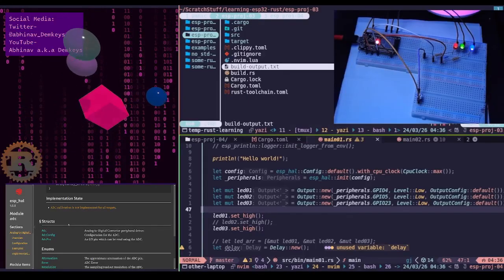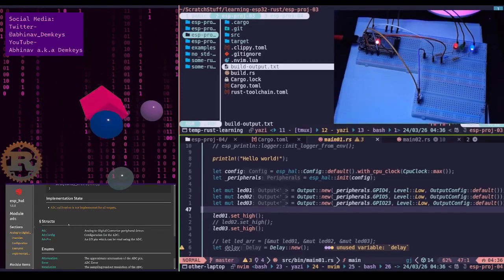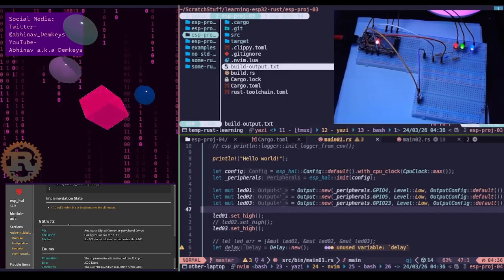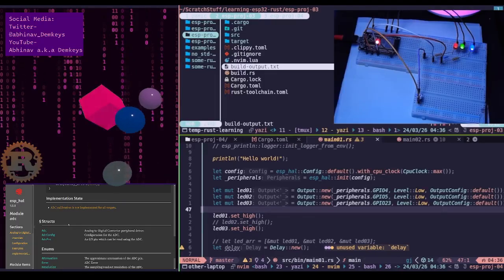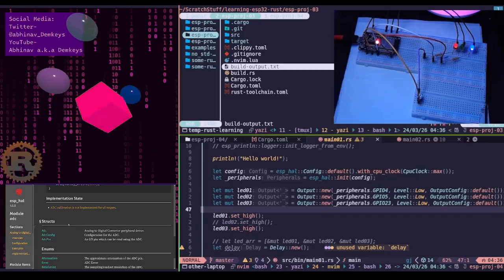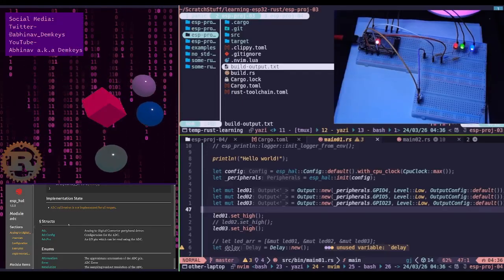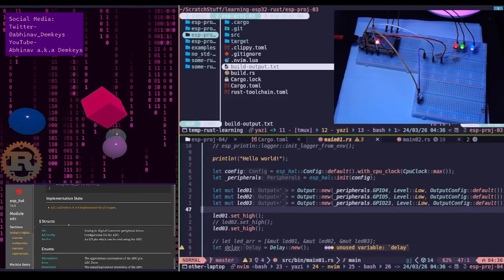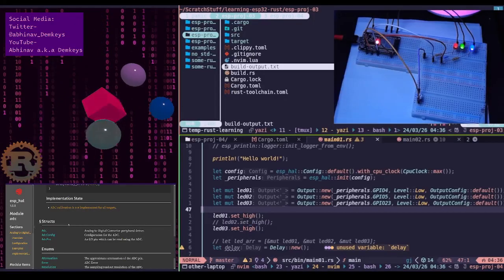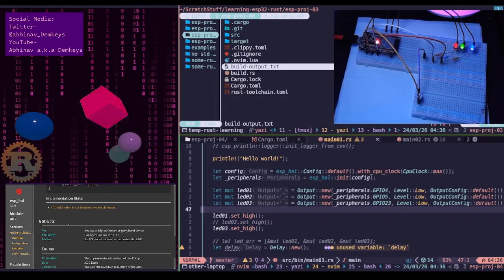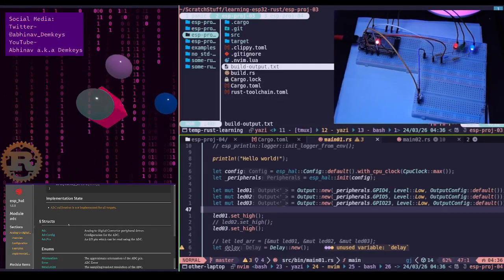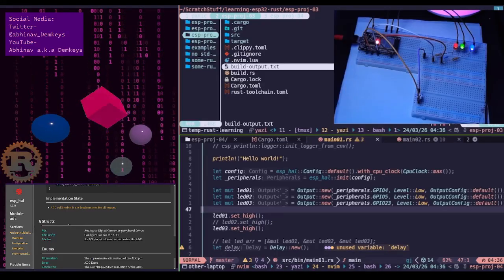To light up an LED, you need around, or well, the usual operating current for one of these LEDs is usually around 10 to 20 milliamps. That's more on the lower range as well. And here they're saying 0.33 milliamps. So this is a tiny safe amount of current that just sits there creating the voltage map for your ESP32 to read. Why don't we use this to power an LED?